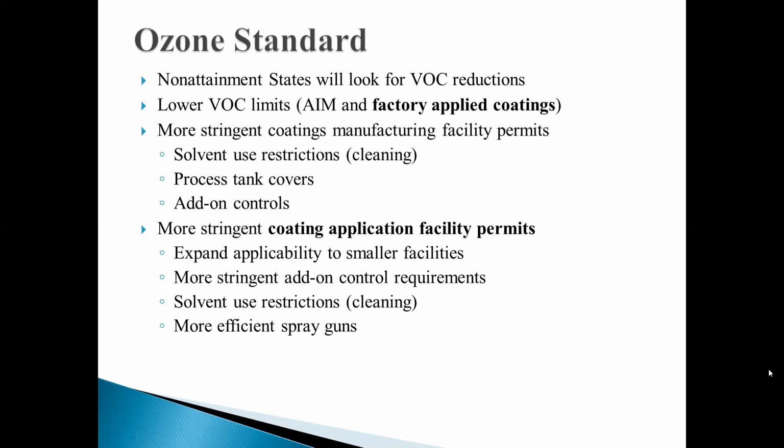But what is really causing this? What is the onus? Why are states adopting more stringent VOC standards? It's the National Ozone Standard, which has been modified about every 5 years. The problem, of course, is when the states are not complying with the ozone standard, they look for VOC or NOx reductions. Coatings is usually one of the first VOC reduction rules that they go after: architectural, industrial maintenance, field applied, and then of course factory applied coatings.